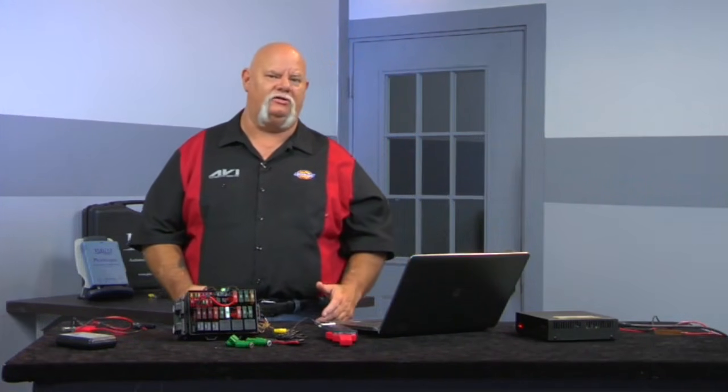We also have the ability to compare injectors on the vehicle for pattern observation. Again, just like the ignition coils, we do not want to see a short or a vertical line or a big giant beer belly. We want to see a defined opening. We want to make sure that the injector current flow matches the other injectors on the vehicle and is in spec for that particular injector.